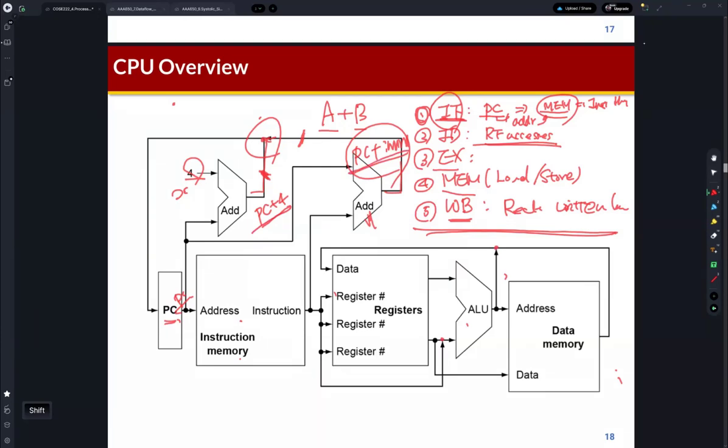What's the problem? This is not allowed, because in hardware design, if two wires are connected like this, then these wires need to have the same values, right? Because as I mentioned, the wires are metal wire, and it needs to have the same voltage level, meaning the same data, right? So this is not allowed. Then how can we handle these connections?